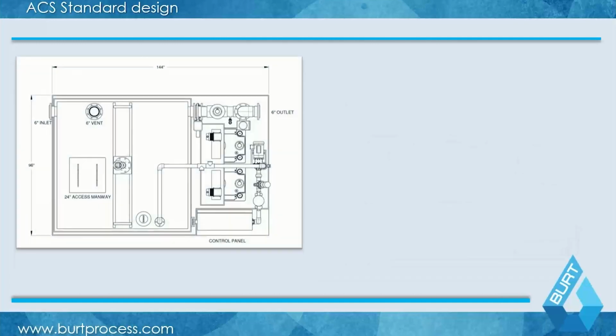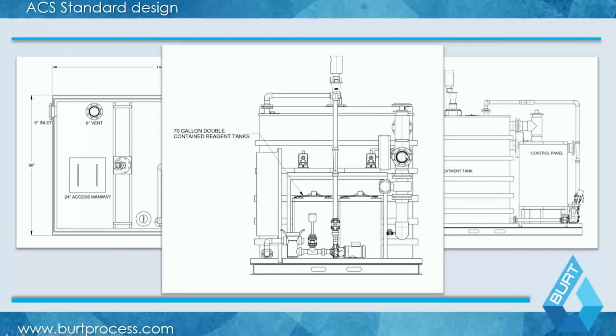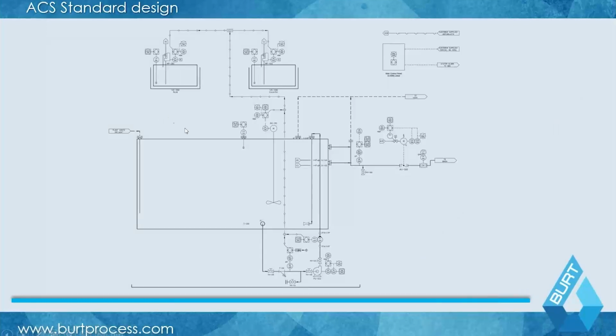And then you have the examples, the drawings here. The reagent tank, the circulation pump, this is your actual treatment system. Then your effluent, where you have basically a dual U-trap configuration, so you have that additional hybrid volume in here. Should you have to go into batch mode, as an option, you can eliminate that and just have it go back to an equalization tank upstream or a lift station as well. And it's just a P&ID on these. That's what I was just referring to here. You have that hybrid batch volume built in here. This is your recirculation loop as well.